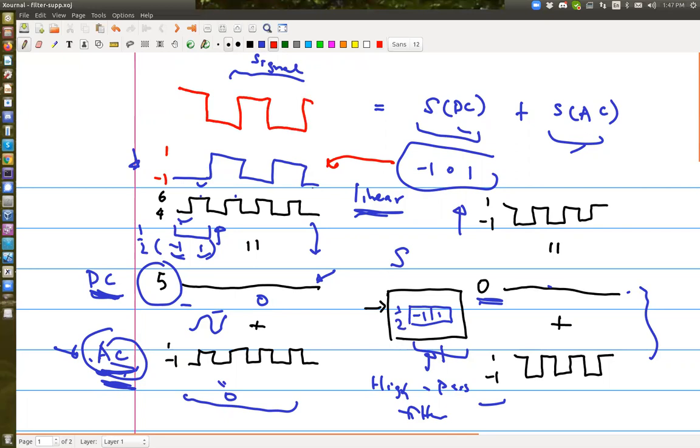So anyway, this signal is again some kind of high frequency signal that will pass through this filter here. But any constant signal is not able to pass through. So it is not an ideal high pass filter, but it definitely will block the low DC, block the constant component there. Therefore, this is some kind of high pass filter.